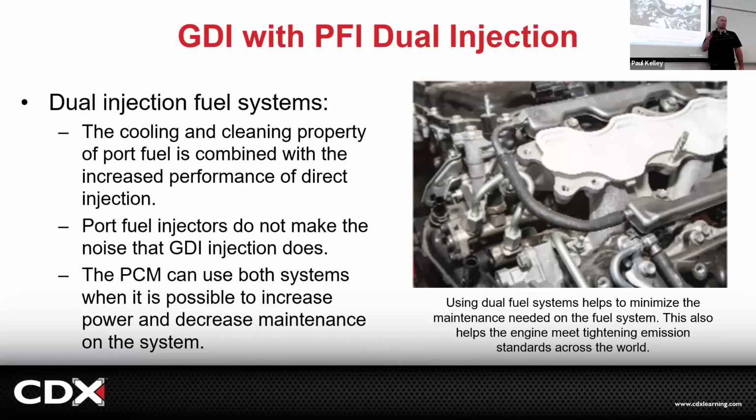diagnosis. There's a function in the scan tool where you can switch direct injection or port fuel injection. So we said, hey, go in there, change it over to port fuel injection, see if it misfires. Then change over to direct fuel injection, see if it misfires. So this is what the former student technician did. Put it on port fuel injection only, misfire totally cleared up.